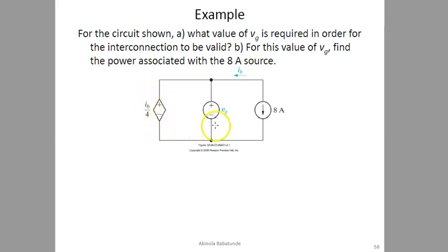All right, so how do we find the voltage on the dependent source? We know that our IB would be equal to -8, because 8 amperes is actually pointing downwards, as you can see with this arrow. Any current that is pointing against this arrow pointing downward would take a negative value. So as you can see, IB is actually going up, so IB will be -8 amps.